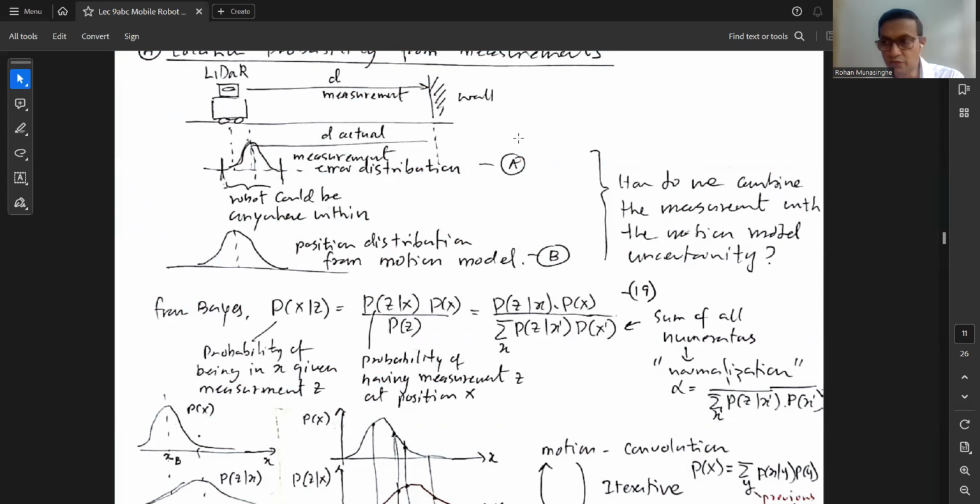The mean is usually zero, which means if you use equipment to measure something, the equipment is not supposed to add a fixed error to the reading, but the equipment or sensor has a noise, and noise is plus or minus. So it's around the measurement, but it does not add any fixed quantity to the measurement. Let's say when you measure your temperature using a clinical thermometer, it is supposed to measure the actual temperature with some noise. It's not supposed to add another degree or two to your body temperature or reduce a degree or two from your body temperature. There's no fixed error, which means there's no mean. Some sensors might have this mu, but most of the sensors, by design, are supposed to make mu zero. All right.